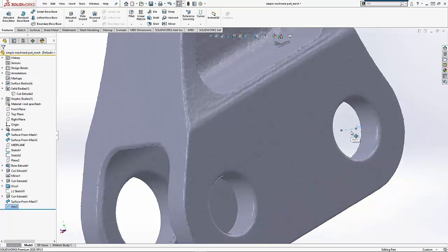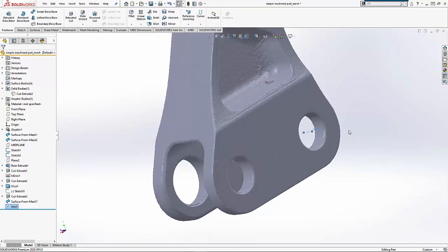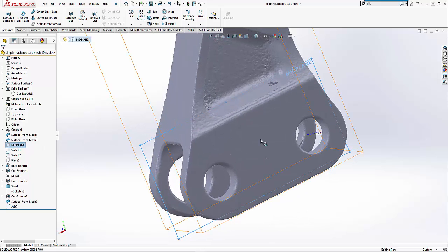Now that axis, we may have to be careful with it. Just like we saw that the angled faces on the surfaces we created right from the beginning were at a slight angle, this axis may not be perpendicular to our midplane, so we may have to just use it to go in and help us locate a concentric hole to put in the part.